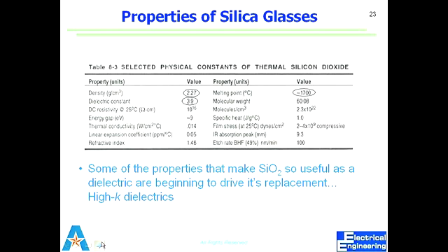So even before mechanical cracking, what it can do is what we call dislocations. It can cause dislocations of the crystalline structure. Dislocation is where you might lose one ball of a lattice, so you don't have atoms there. That results in electrical degradation of the behavior of the device.